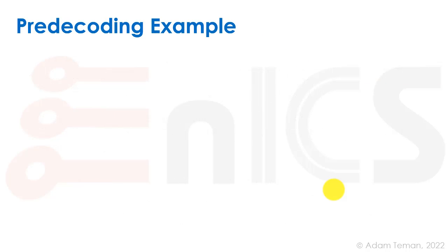Again, let's go back and show how we figure this thing out. What we have here is our post decoders over here. We're going to have 1 per each word line. These guys are going to get inputs of some sort, and I just defined in the question that these have to have 3 inputs each. They're going to be 3 input AND gates.